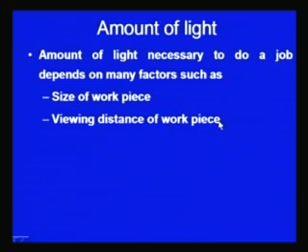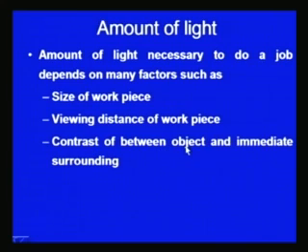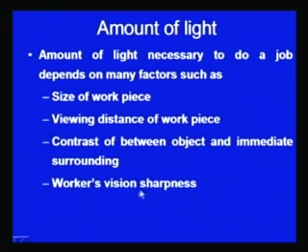So, an increase in size of the job reduces the light requirement, but for fine jobs more light is required. Regarding viewing distance, in general, an increase in the viewing distance of the worker increases the amount of light required. If the contrast between the object and the immediate surrounding is low, then more light is required, otherwise low light is enough. The worker's vision sharpness also depends upon age, so the amount of light required for doing a particular job varies significantly.